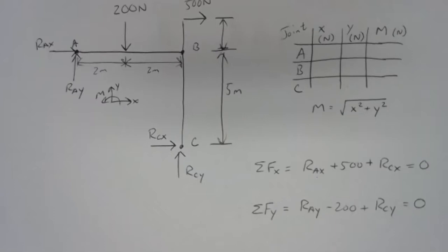And this is where we have to be really careful. Moments can be tricky already in a truss problem because horizontal and vertical moments can come into play. In trusses, we always found that we could pick a pivot point that would give us an equation with only one unknown. That's not always going to be true with frames. When we figure out the equations of equilibrium for a frame, there may not be a point we can pick to guarantee us only one unknown.